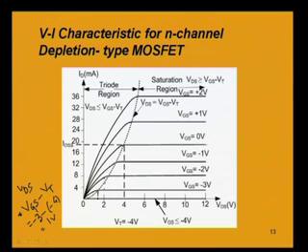When Vgs is equal to 0, we know that we have got this IDSS, that is the drain to source saturation current when Vgs is equal to 0. Now, this region between cutoff and the drain to source saturation current at Vgs equal to 0, from this point to this point, is where the depletion phenomenon is going on. So, this is the depletion region.